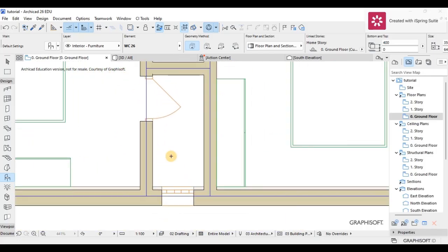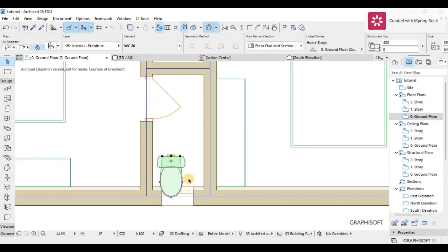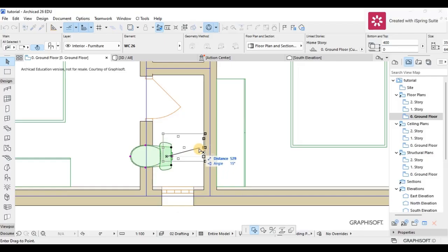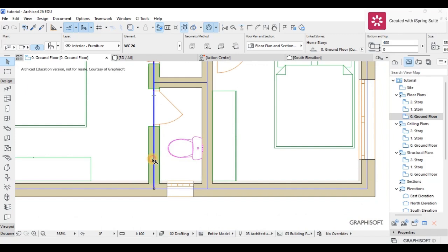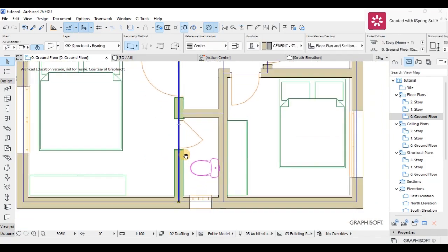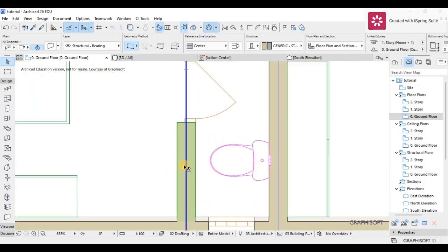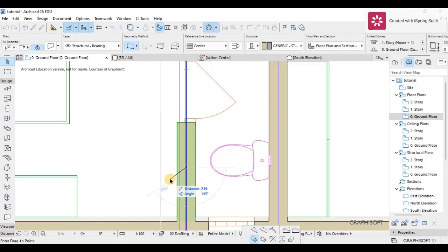My bathrooms are small, so I'm just going to fix that a bit. So I'm going to now Control E this one so that it can go like this, and maybe drag it somewhere like this. Let me see if that's going to help. Yeah, so with that said, it will force me to increase my bathroom in terms of the width. So I'm just going to increase this one. Let me just drag this wall here.